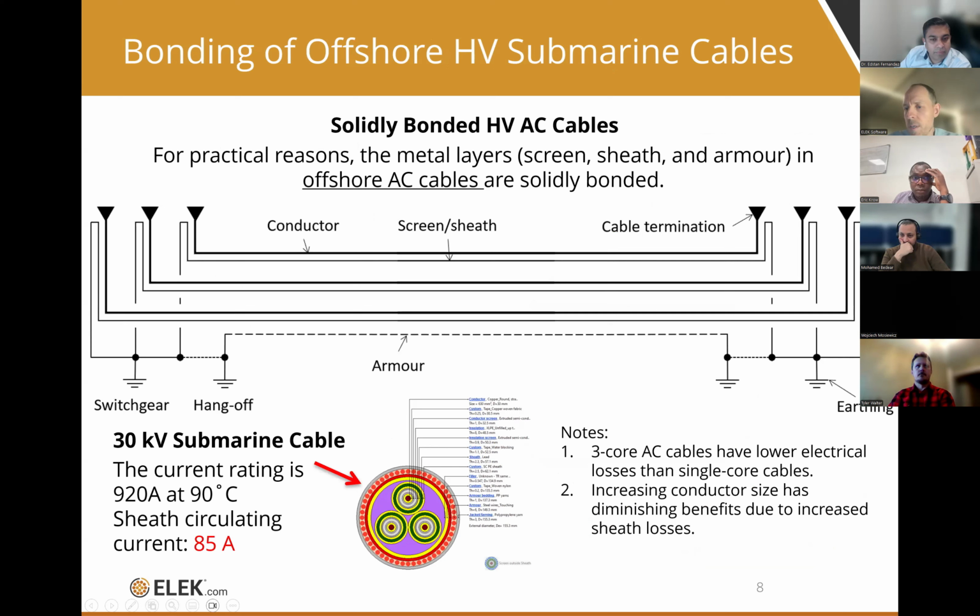The bonding, we need to mention the bonding of these three core submarine power cables as well. Due to practical reasons, these cables are solidly bonded at both ends. Therefore, the disadvantage of that is that you have circulating currents within the armor and the sheath.